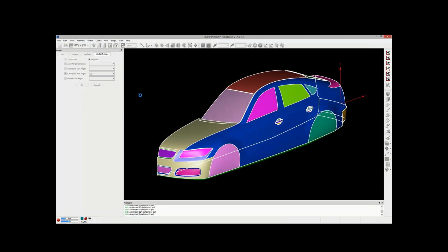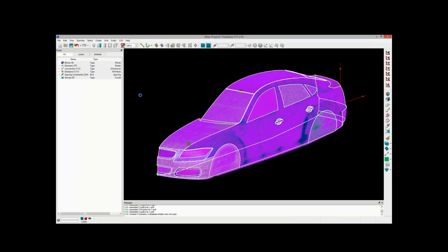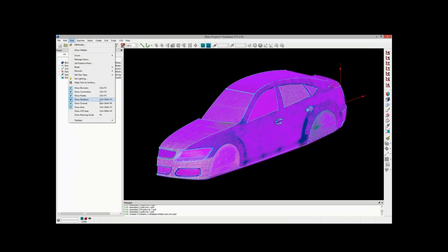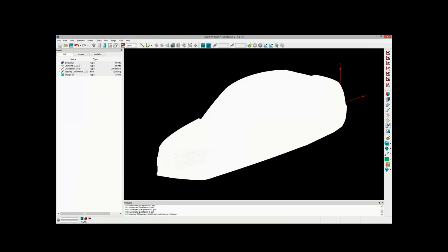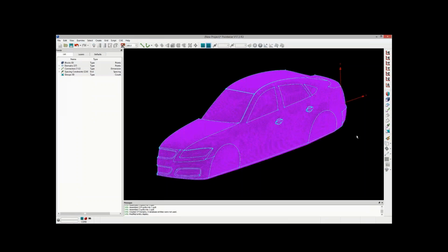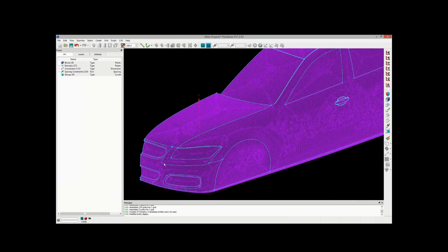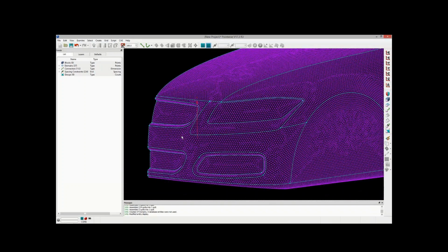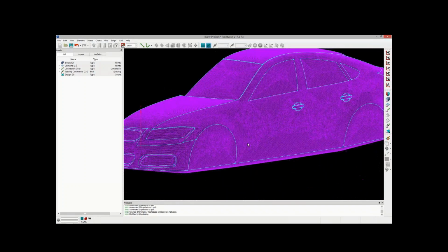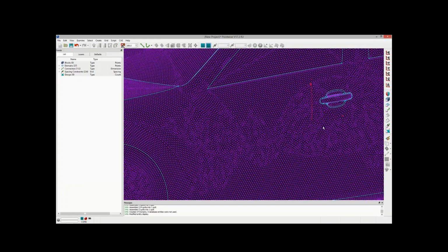You can turn those on. In my process, I like to create a uniform surface mesh and then go in and refine after the fact. Maybe the point to make here is that you're never stuck. If you don't set up these constraints first, like the curvature-based refinement, you can always do it afterward. That's why I feel I have a little more flexibility if I create a uniform surface mesh and then go refine afterward, modifying the attributes of my grid curves and surface meshes.